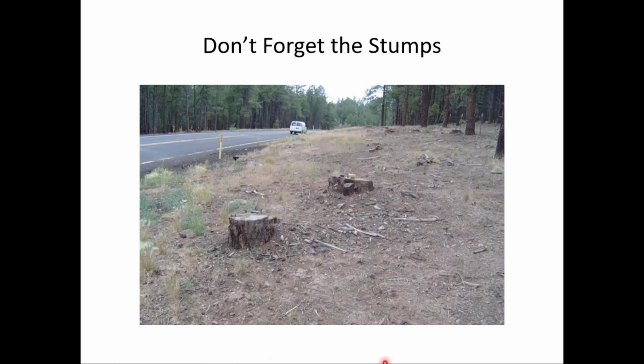And don't forget the stumps. I commend this agency for removing some trees, but the general rule of thumb is the stump or bases like this should be no more than 4 inches high, and these look like they're more than 4 inches high.